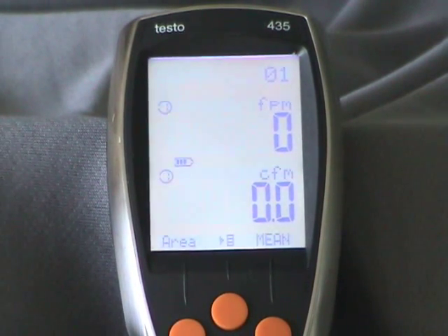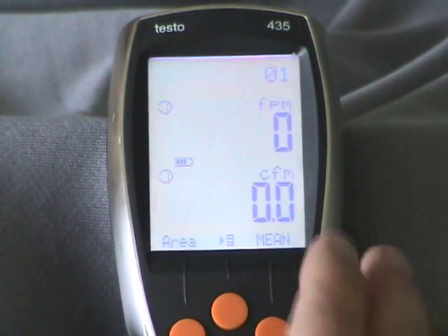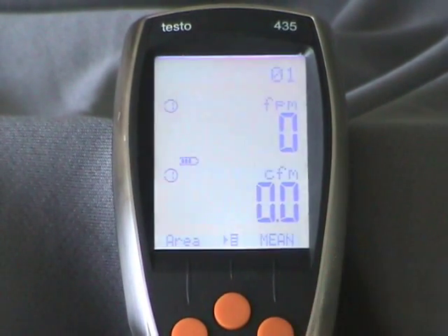In my part of the country, where flex duct is the rule, it's easier to take an airflow measurement at the return air grill than it is to try and get into a short supply plenum where you don't have 30 inches of duct to insert the mini vane anemometer. That's where the 2.4 inch rotating vane anemometer shines, for things like that.